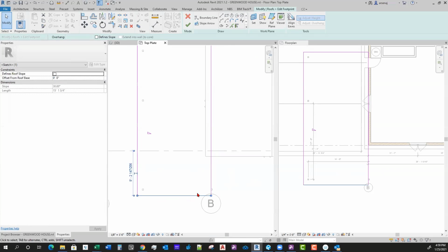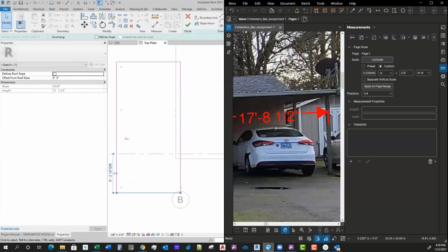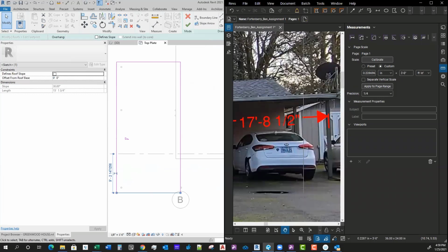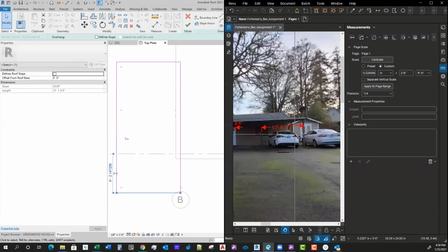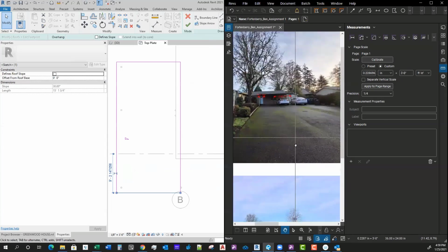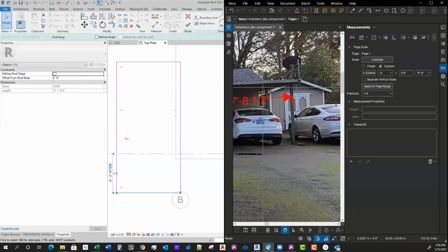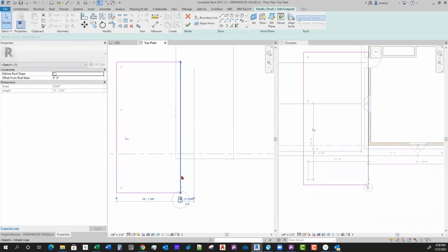And so now it's got the correct offset. So now I'm going to add additional boundary lines because although I can't tell, and this is the part where you get to use your imagination, since we can't see this side, we can just assume that maybe it just goes back here and then ties into the roof back or into the wall back here, but at that same slope.